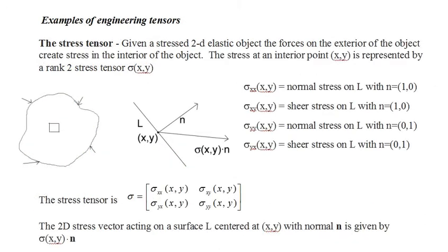Now we have covered the theory of engineering tensors. In practice and in text, tensors are always shown as matrices, and the operations on the matrices are the familiar matrix operations. You'll never need to explicitly compute a tensor product or contract a tensor in practice. The only formula that we've covered that you might actually see is the formula for calculating the coefficients of a tensor, i.e. matrix, following a change of basis. So the theory of tensors, and particularly engineering tensors, is pretty simple.